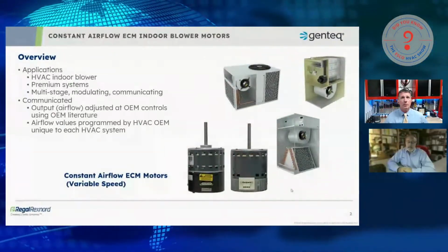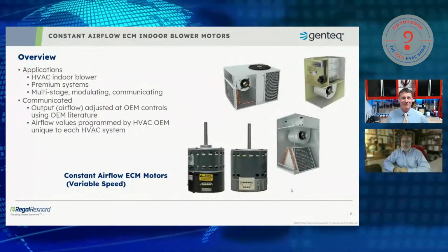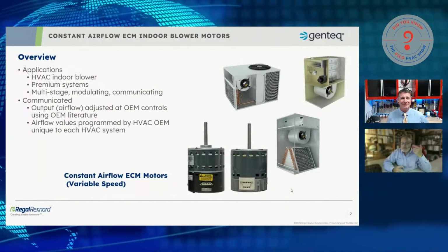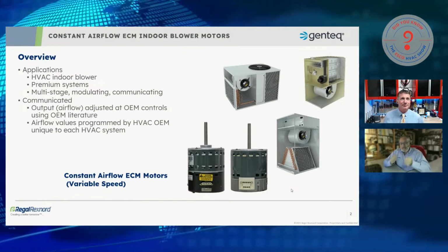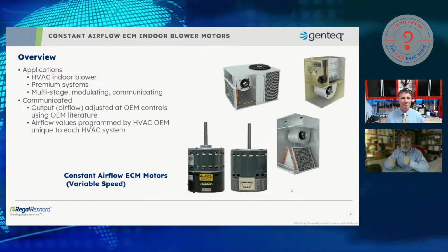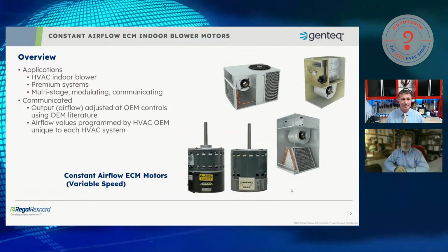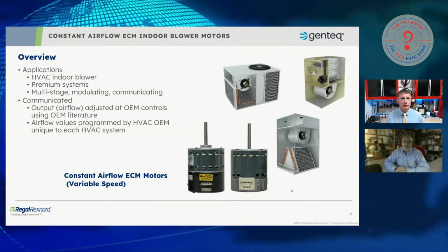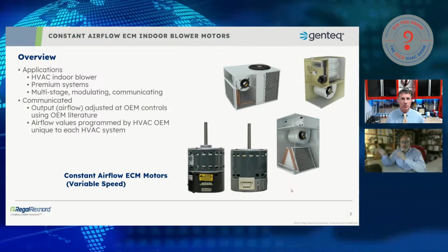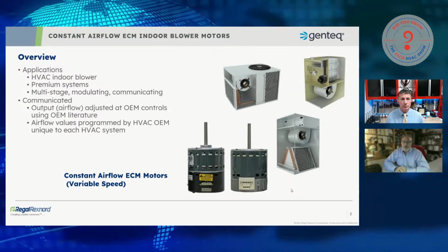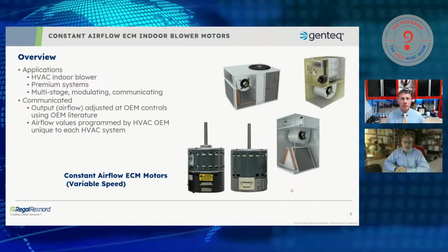These motors are also what I like to call communicating, and I like that word because it immediately says something different than multi-tap, multi-speed. You're not going to be moving wires from one tap to another to change the speed of the motor. You're going to be doing something else, because the motor is actually communicated with information from the OEM control board to the motor, which dictates how the motor performs.